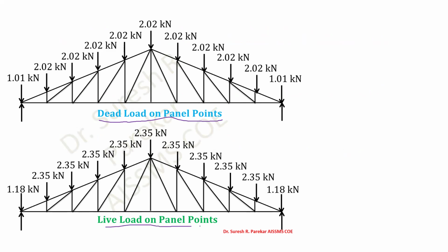panel points. So we are not considering wind load, because the reaction due to wind load is in upward direction and we have to design the column, and therefore we have to consider the combination of dead load and live load only, not wind load. Now reaction due to dead load, so we have total load.